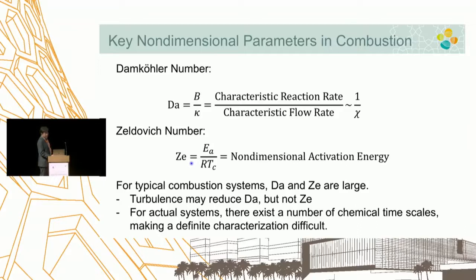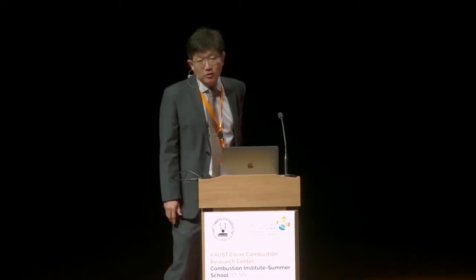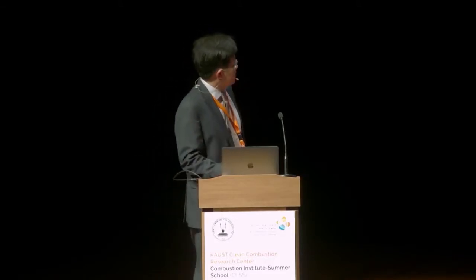What I'm going to point out is that in the typical combustion systems that we are dealing with, these 2, the Damkohler number and Zeldovich number, are typically very large. And that is the main reason why the problems are difficult, because it poses a lot of strong nonlinearity in the problem. All these nonlinear problems are harder to analyze and predict.